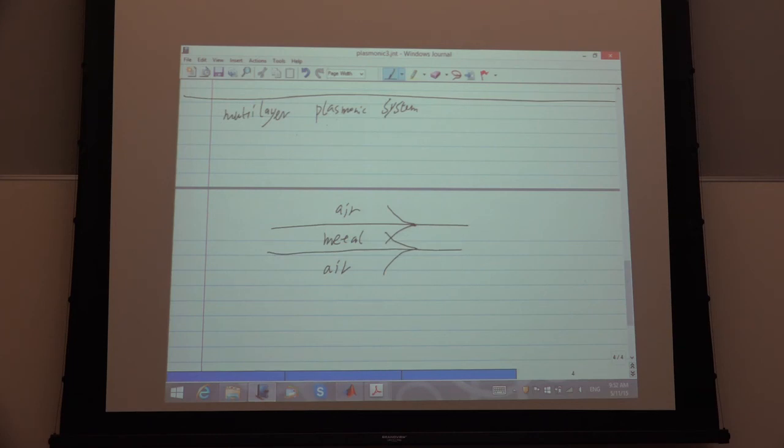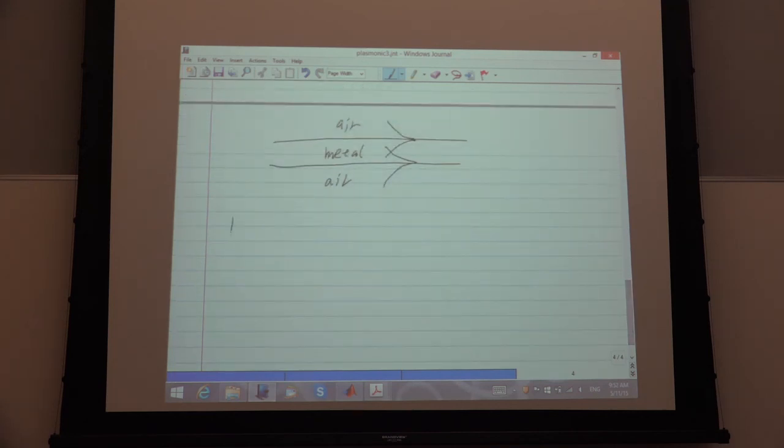When they interfere, according to coupled mode theory, they split into two eigenmodes. At first there was only one eigenmode, now there are two. These eigenmodes have a very interesting feature that we call long range and short range. I made a picture to draw this. It has two band diagrams, Re beta versus omega. This is the real part of the propagation constant.